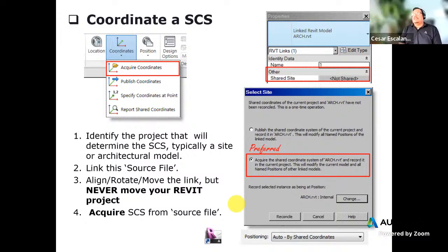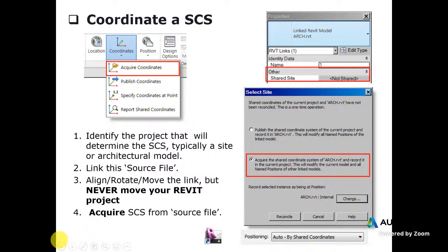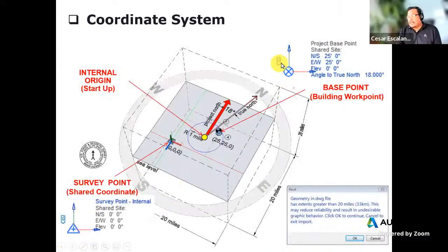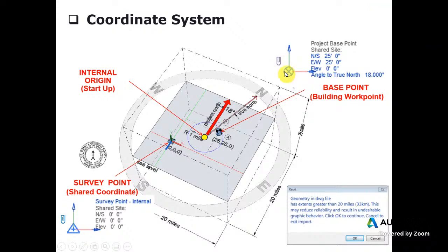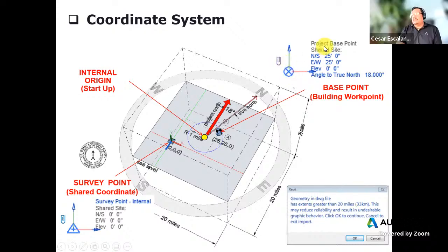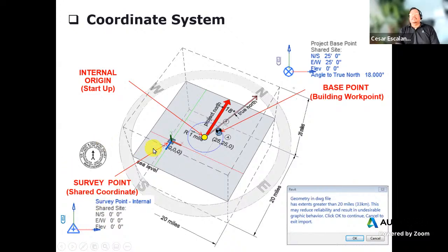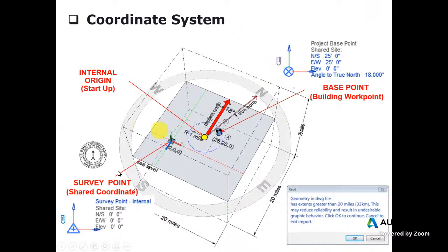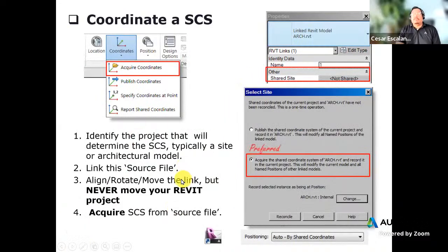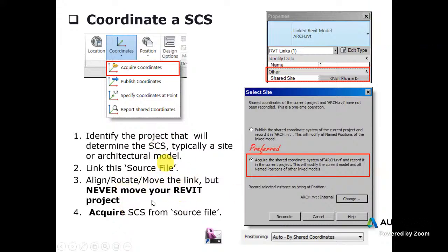Yeah, that is a property of the project base point. Let me show you. The project base point has this clip state. If you move a project base point in a clip state, you're basically shifting the world. You're moving everything, the views, but the only thing that's staying behind is the survey point. And so that's the proper way of shifting a building. But you don't select everything and move things. Perfect. Thank you. And we'll do an exercise to show you how to.